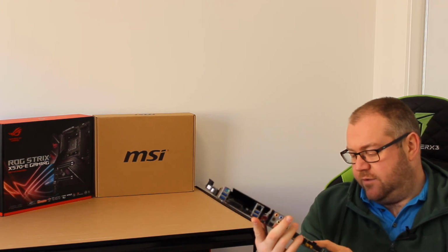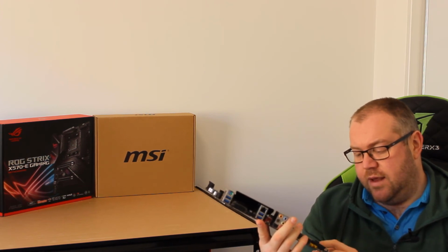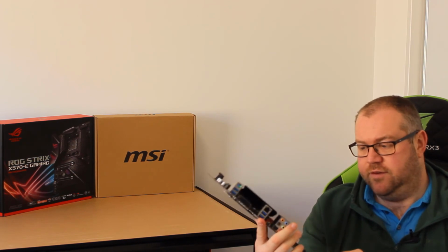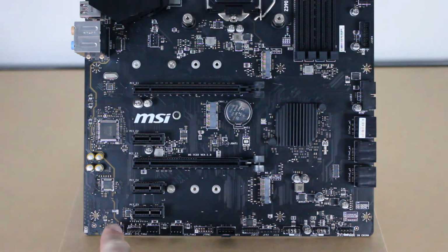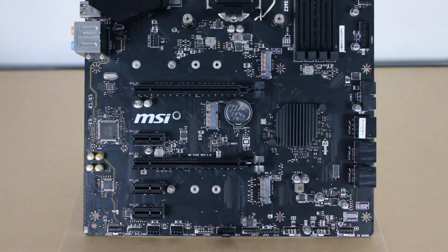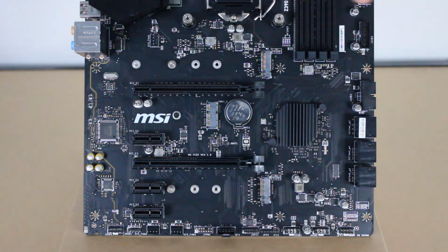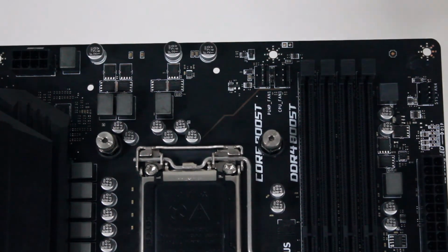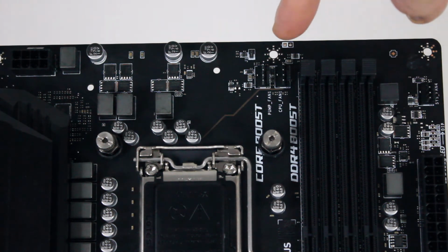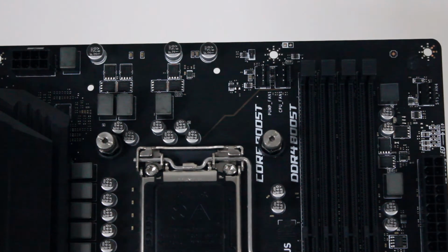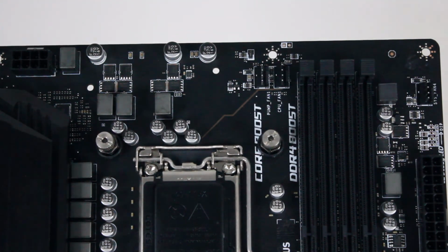You'll have a bunch of other USB headers, and then everything is labeled. So here I've got system fan 1, system fan 2 that run across the bottom here. The audio output for the front, so your front audio ports. Another system fan there, which you plug your back case fan into. And then up the top, you've got the CPU fan. So if you're running an air-cooled CPU fan, you plug it into there. And then there's also a pump fan as well. So if you've got an AIO or an all-in-one water cooler, you can plug the pump into that too.